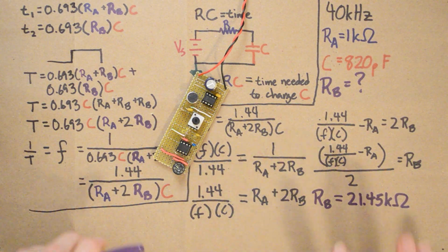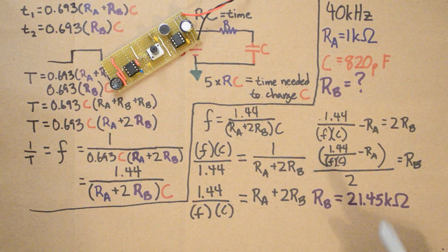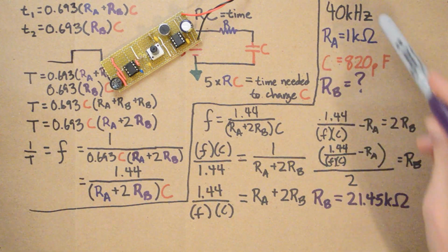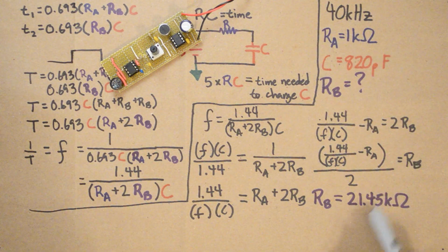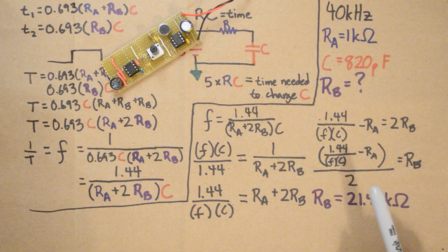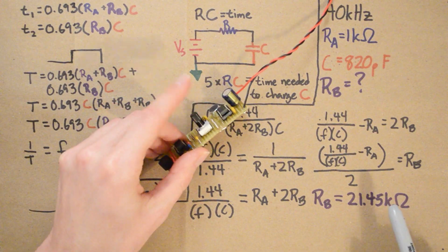So this is great to get you close, but remember there are factors that when you actually build a circuit come into play that may not get you exactly 100% on target of 40 kilohertz or to your target value. Remember, every one of these components has a percentage error. There could be a percentage error in the capacitor and the resistor. All those percentage errors put together could lead you off of this, and probably will. So you need to design to account for that fact.